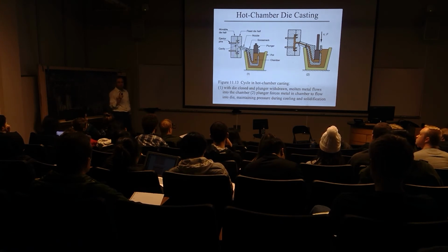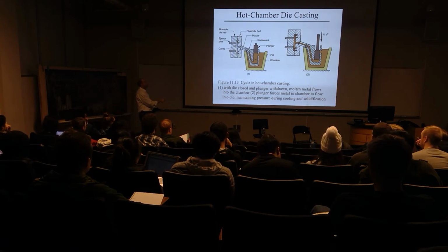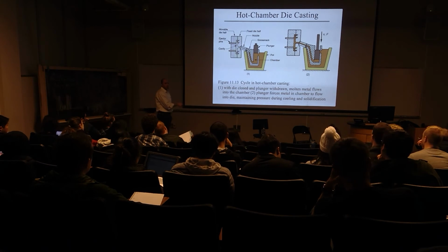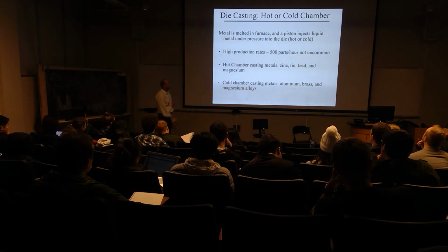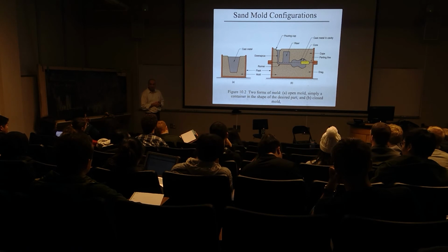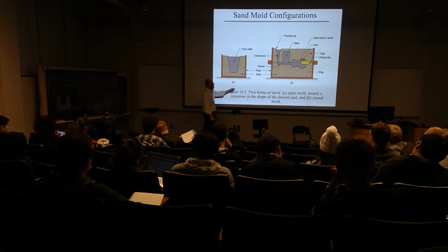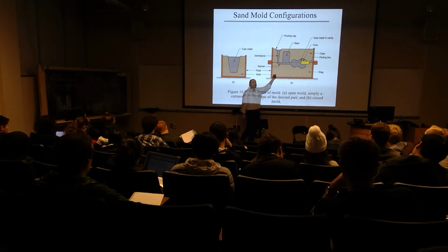This is important from a defects analysis because of the following. These are metal, and metal has a certain thermal conductivity that's different from that of this material. And what is that relationship? Of course, in this case, the sand is mixed with a small amount of clay and a small amount of water also to hold that assembly together.